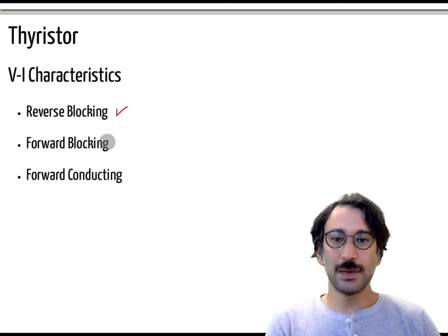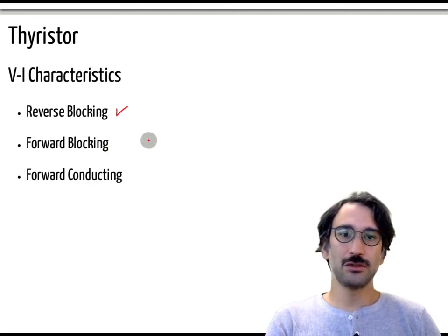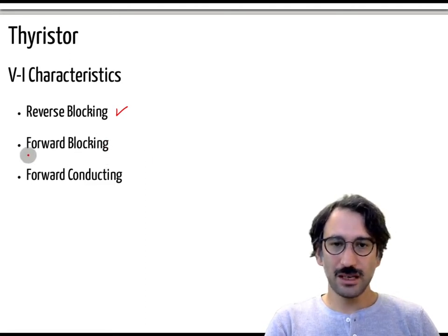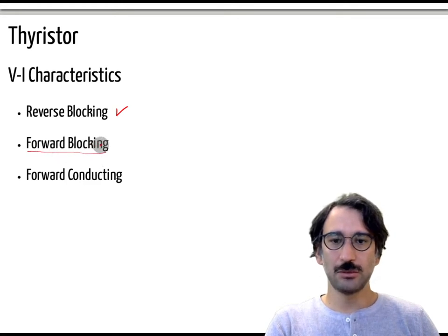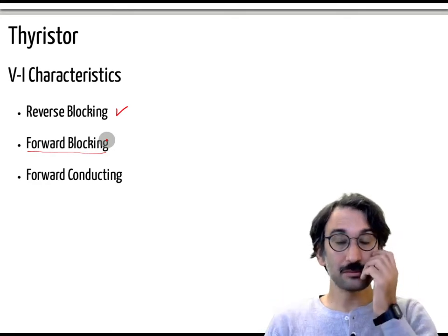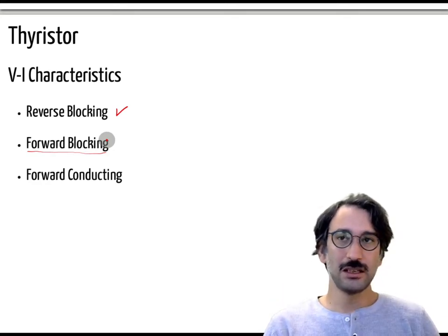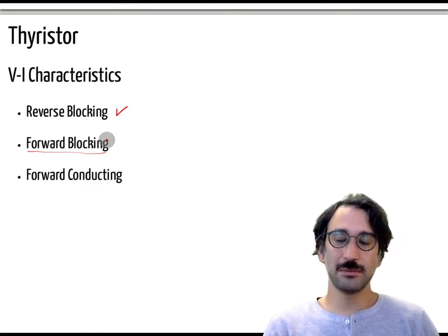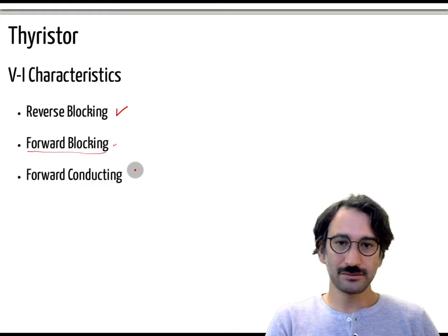So it is the maximum amount of voltage magnitude that the thyristor can withstand without damaging. And apart from a diode, now we have the forward blocking. So you don't apply a gate signal and it will block the current. Then you increase the voltage, then it is forward bias, but as long as the gate signal is not applied, then it will not start conducting.